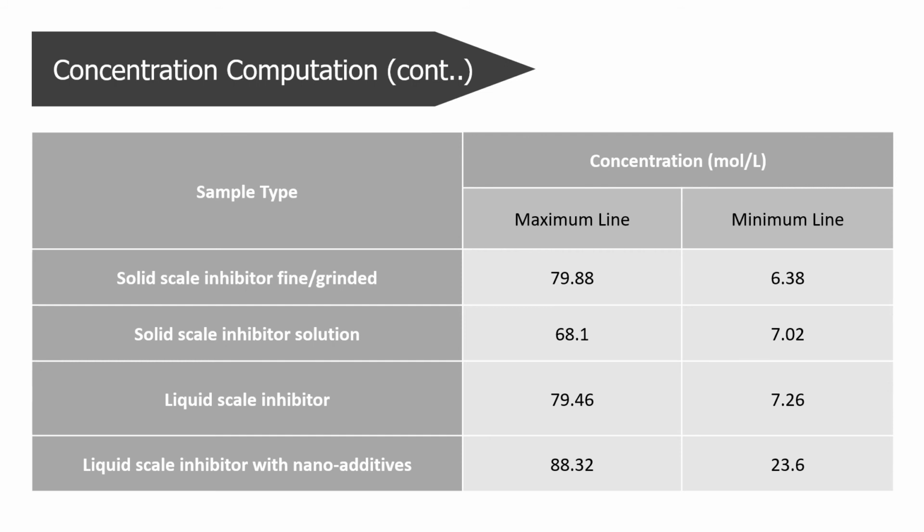This means the absorption of scale inhibitor to the resin coated glass bead is increased. The distribution of the liquid scale inhibitor with nano additive graph also shows a more stable pattern, hence the resin coated proppant still carries a high concentration of scale inhibitor that can be verified and is also slowly dissolved.